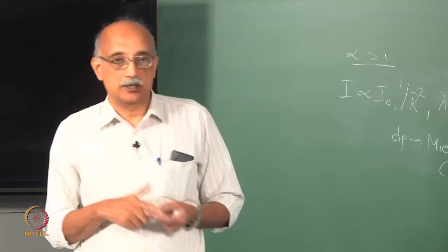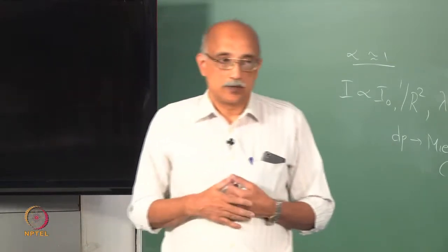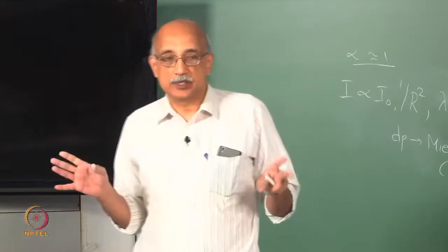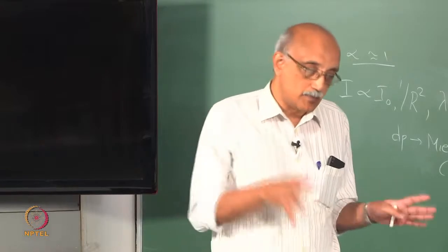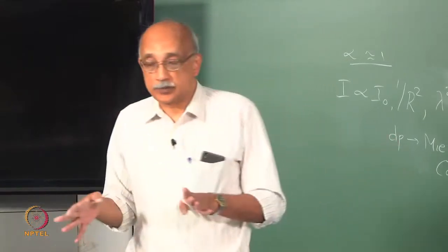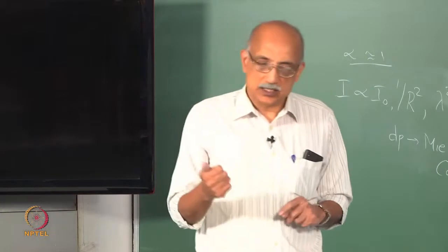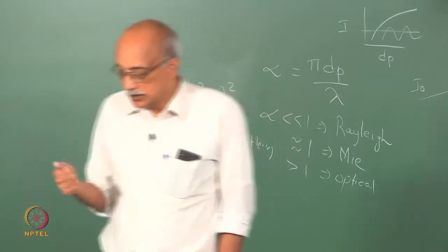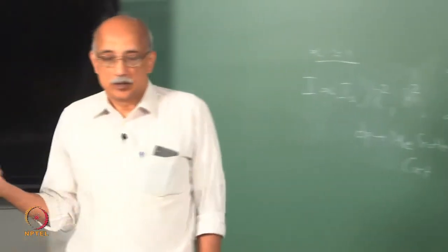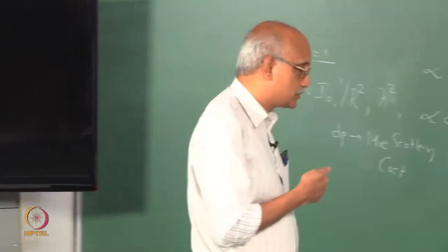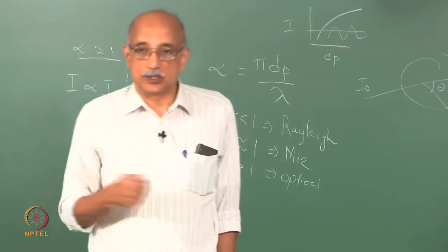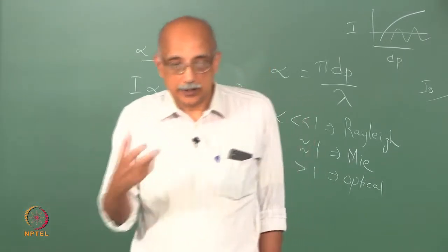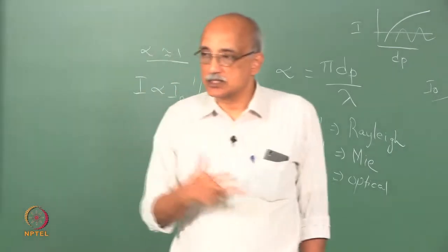Together, repeatability and reproducibility errors, if you add them, that is called the gauge capability of the instrument. The gauge capability of an instrument is a sum of its repeatability and its reproducibility. So it is not just a metric for the instrument, it is actually also an indicator of the procedure, because a procedure is really what drives particularly reproducibility. The procedure for the measurement has to be well enough defined, and it has to be clear enough that two people can follow the procedure and get the same reading.